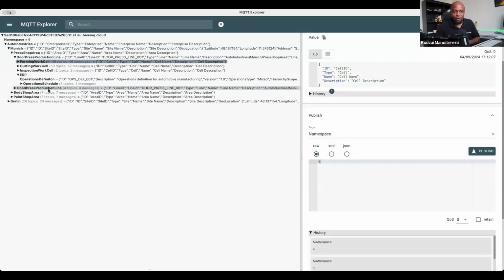This is also one of the questions I get a lot: how does the unified namespace replace ISA 95? The unified namespace still preserves the principles of ISA 95, but it's no longer a pyramid. It's now a network-structured architecture. As you will notice here, this is an implementation of ISA 95 Part 2 activity models, all those activity models that were defined on exactly how you should exchange information between ERP or business and your control system.